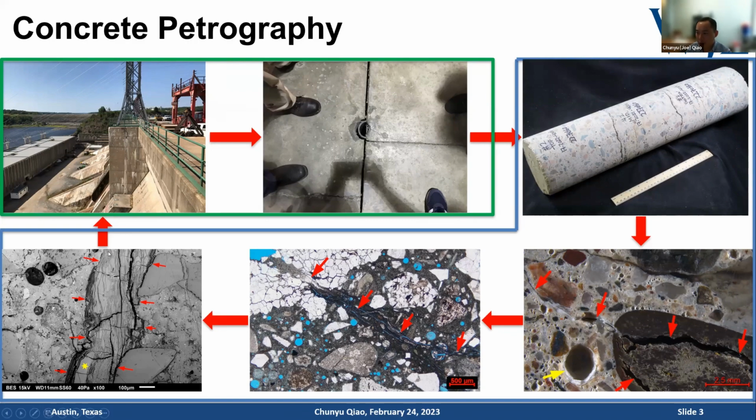On the left bottom, we can see this gigantic crack is filled up with ASR gel. Different element compositions in the gel can show different gray levels in the SEM image. So we can do EDX analysis to see if the gel is rich in calcium or rich in alkali, which can help us identify the age of the ASR gel. Together with optical microscope inspection and SEM EDX analysis, we will have a thorough opinion about where this ASR reaction stands within the structure right now.